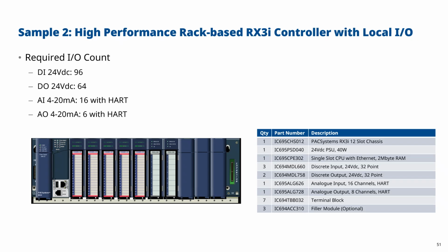If it was just analog inputs with HART only and we didn't need pass-through, there is now an RSTi-EP HART module, but it doesn't include the full HART pass-through, it just has some HART capability. Another possibility might be to use external HART multiplexers, but again, what I want to do is provide Emerson components without too much third-party complexity.